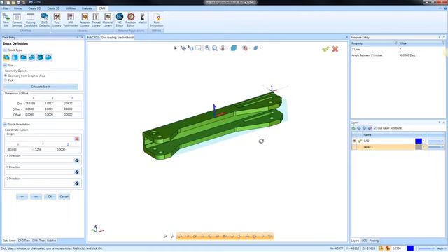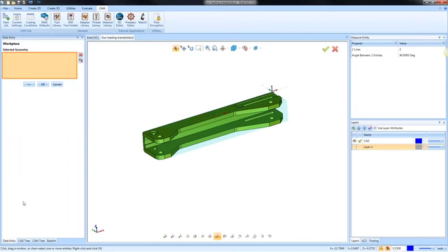Travis had a question. So do we draw stock? If we draw stock, we use the previous page you skipped to show it in simulation. No, Travis. The previous page, this one here, is for your workpiece, not your stock. If you want to select your part model as your workpiece, your part model is your workpiece. And I'll get into this a little bit more when we get into simulation.